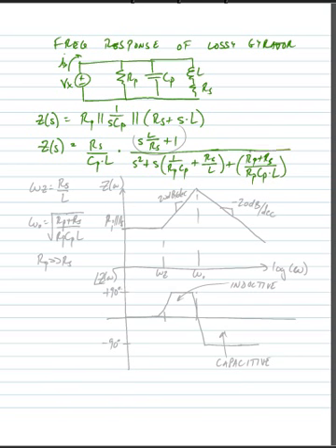And what we would see with this circuit is, if we were to plot the impedance, we see that we have a 0 and we would have 2 pole frequencies. So at DC, the magnitude of the impedance would be equal to RP in parallel with RS.